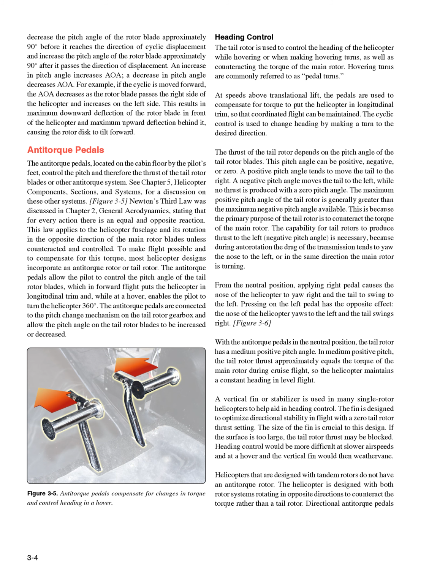Antitorque pedals. The antitorque pedals, located on the cabin floor by the pilot's feet, control the pitch and therefore the thrust of the tail rotor blades or other antitorque system. See Chapter 5, Helicopter Components Sections and Systems, for a discussion on these other systems.